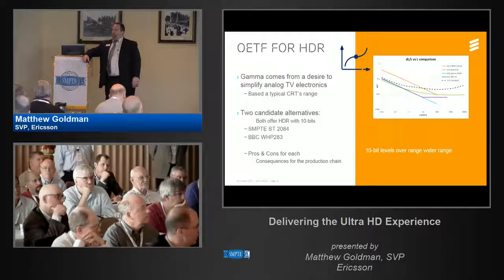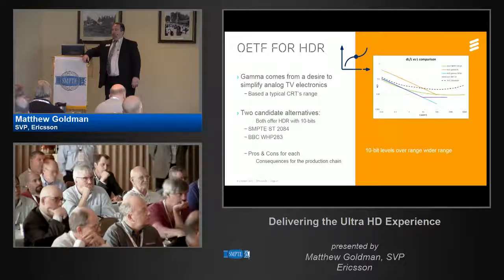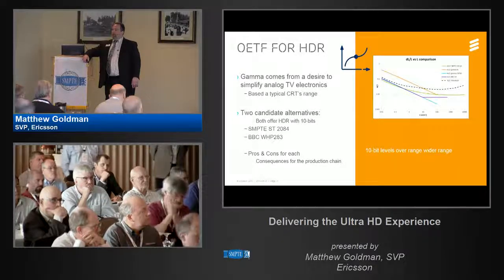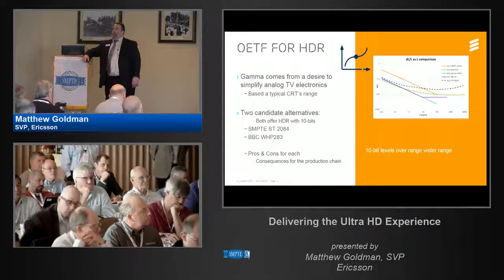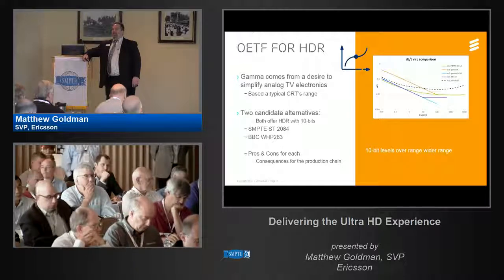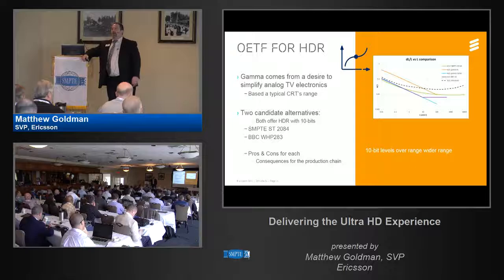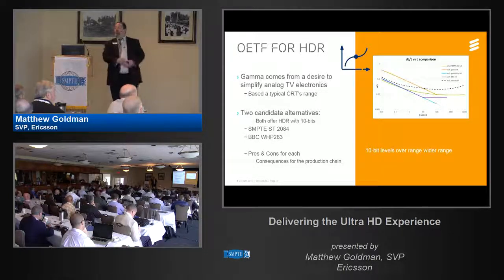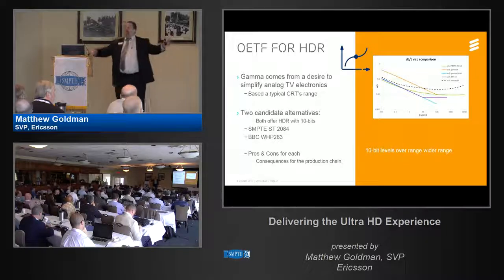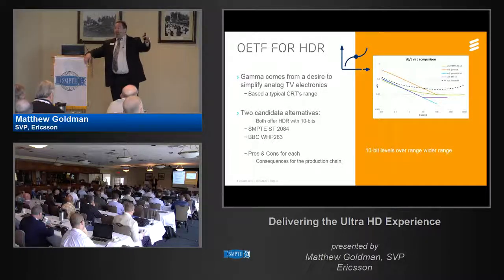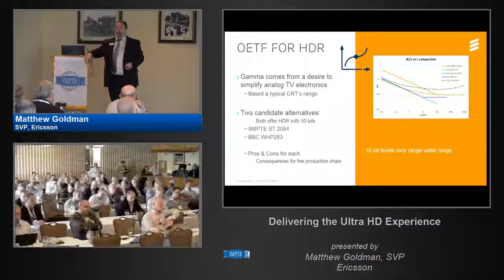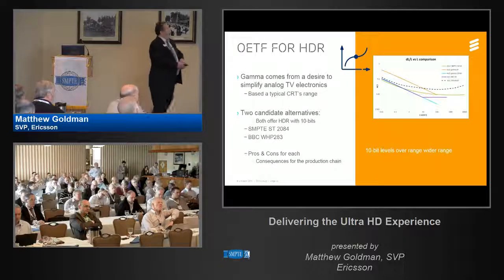Is high efficiency video codec the only codec ready to go right now for delivery that won't concatenate the 10-bit? It's the only compression standard in an international standard that's available today for the home or for consumer devices that does 10 bits 420. There are other standards out there, but they're either for production, which means it's 422 or 444, which means the bit rate's too high for the home, or it's not an international standard. So yeah. All right.